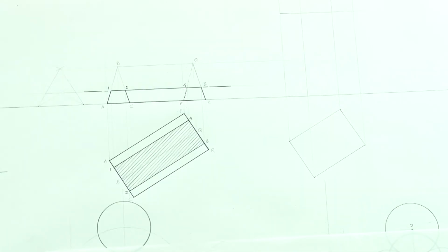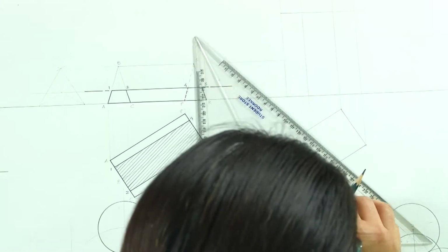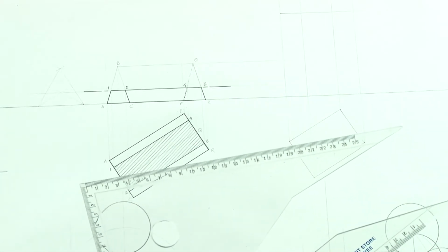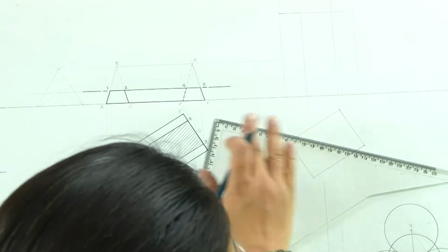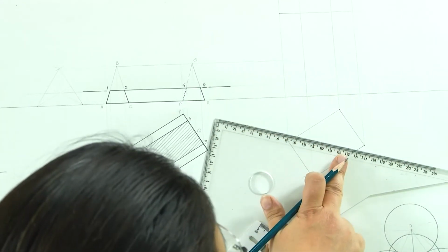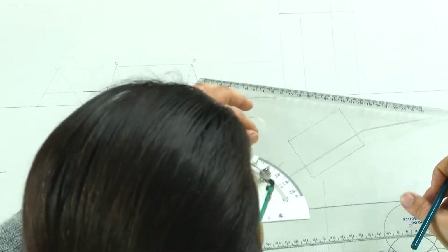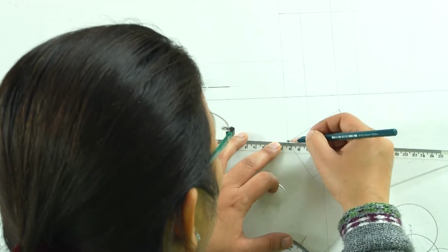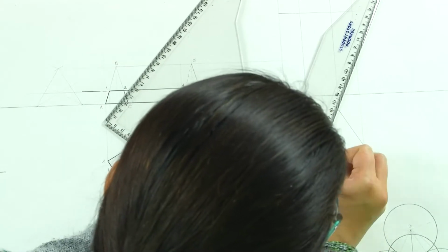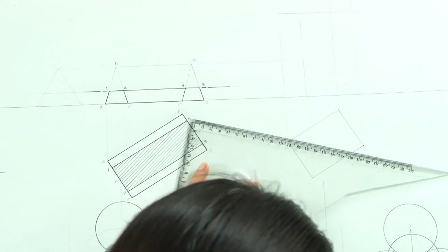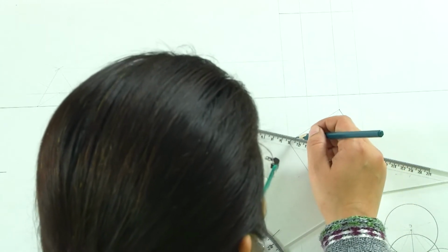Now, let us assume that this rectangular prism is cut by a section plane which is perpendicular to HP, but it is making an angle with VP. So, let us assume that it is cut by a plane which is making an angle of 15 degrees with VP and it is perpendicular to HP. So, when it is perpendicular to HP, what do we see? That one of the lines of the plane is actually going to be parallel to HP, which is what we will see in the true shape here. Now, assuming that this plane passes through the center of the rectangular prism and it is inclined at 15 degrees to VP, this is how the section plane is going to be. So, this is our section plane here.